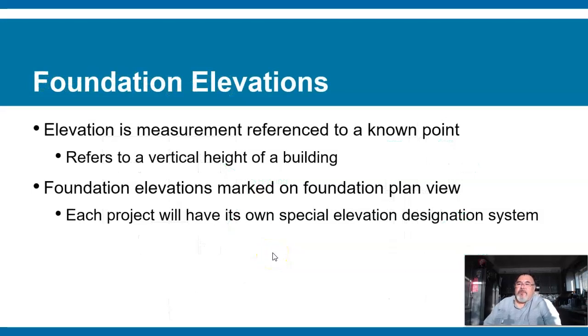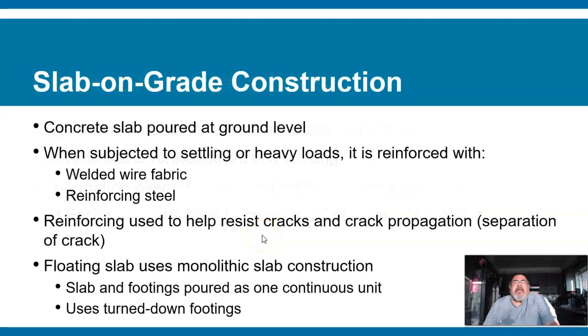Elevations of foundations. It's a measurement referenced to a known point, and it's a vertical height of the building, right? So we're looking at the elevation from the lower section to the upper section from the side view. A foundation elevation marked on a foundation plan view. Each project will have its own special elevation design system. So it's just saying there's going to be a way that you get to read them. They're going to look similar.